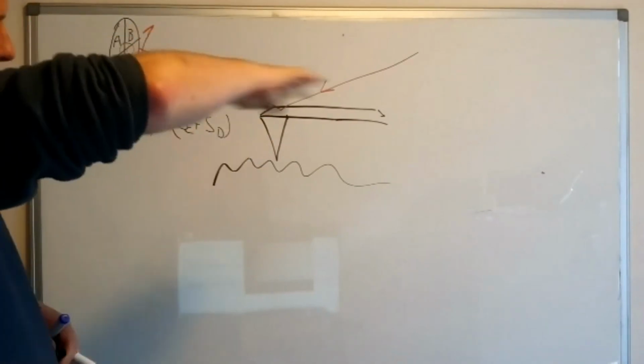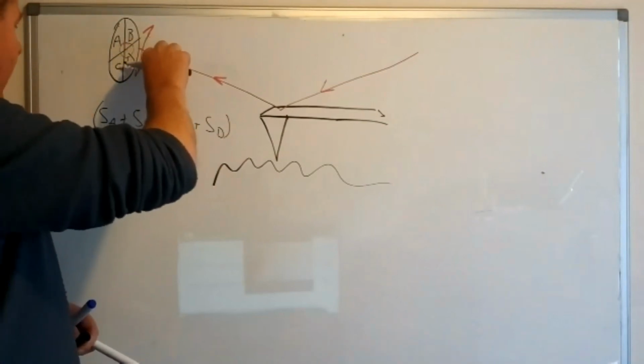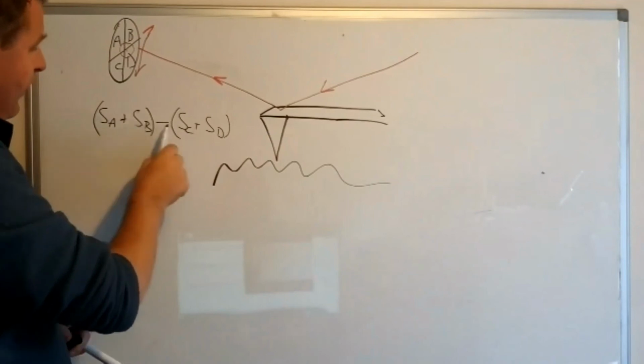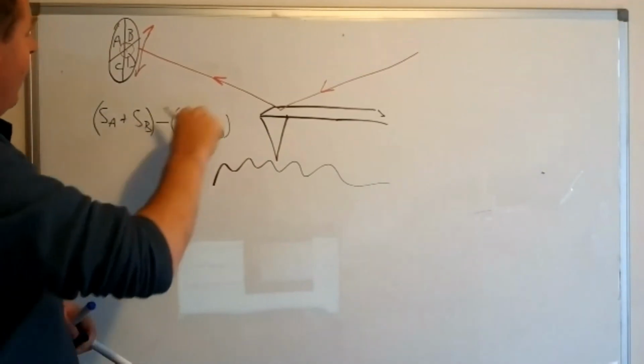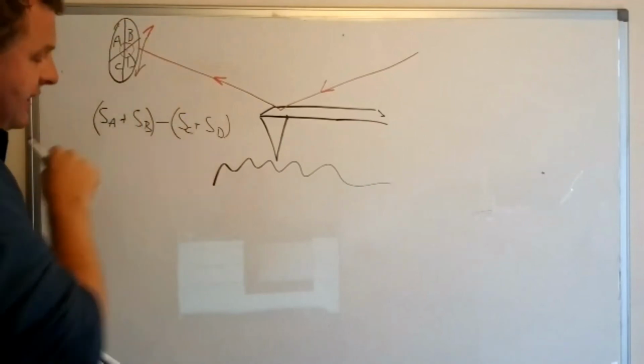Then when the cantilever moves down, the laser spot would hit more onto C and D, so the overall signal we're looking at will go negative, and likewise when the cantilever moves up and light falls more on A and B, the signal goes positive.